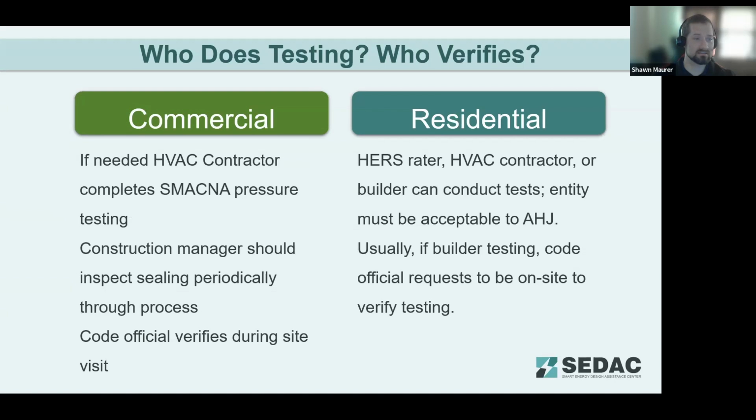Who does the testing? On the commercial side, it's usually going to be your HVAC contractor that completes that pressure testing. One thing that is detailed in that pressure test manual is, as the designer, you need to specify the pressure class for your ductwork. Otherwise, they assume a certain leakage class level, which may not be in compliance with the energy code. So specify the leakage class for the ductwork that needs to be tested so that the contractor knows that the testing needs to be done and it needs to meet that specific requirement.